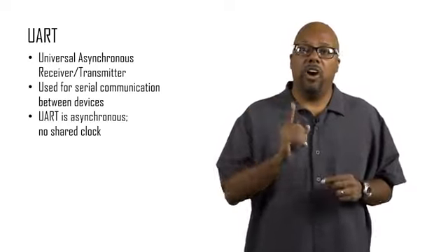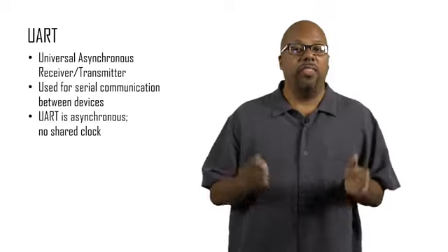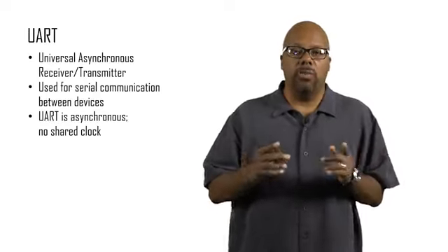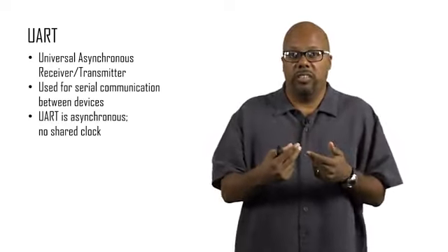And a motherboard can be bigger than this. So what this is saying is that in a clock period, even the fastest signal can't travel from one end of the board to the other. And remember that our electrical signals are traveling a lot slower than light is. So the reason I bring this up is because guaranteeing that every device in the system receives a rising clock edge at the same time is extremely hard, because they're all different distances away from wherever the clock generation is.